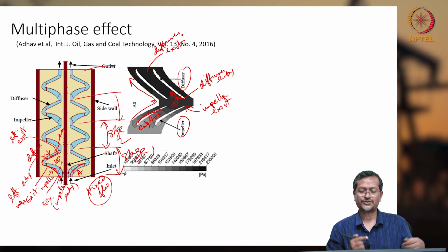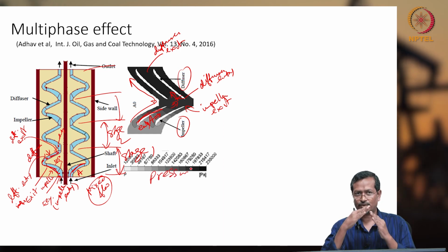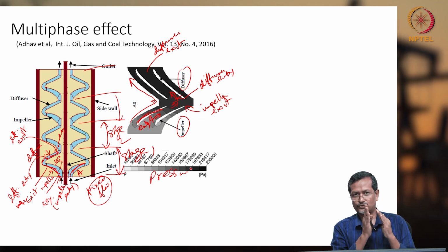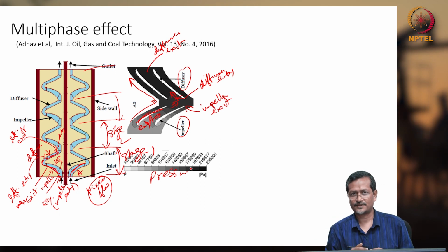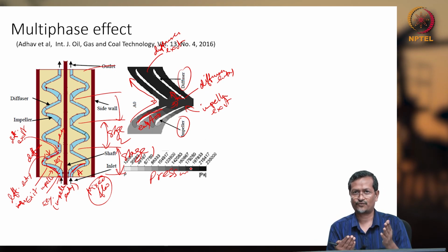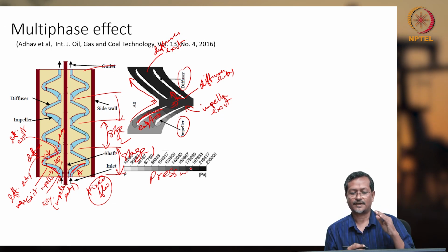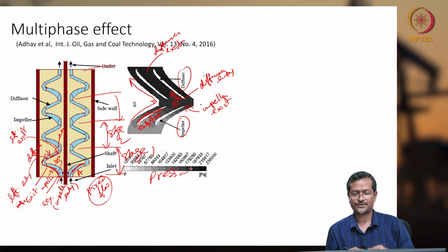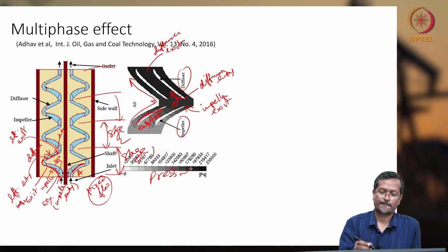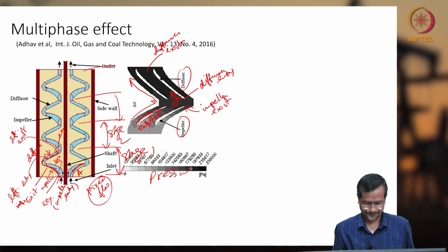And you can see the pressure. This is actually a pressure picture, showing how pressure is increasing. At inlet pressure is low, then going to impeller exit pressure increases, and the diffuser is completely black here, so pressure is already developed. Velocity is very low and pressure head is increased. But inside the impeller, velocity head is higher than pressure head, so that's why this picture is showing like this. It is showing one direction, but three-dimensionally it will be rotating like this.